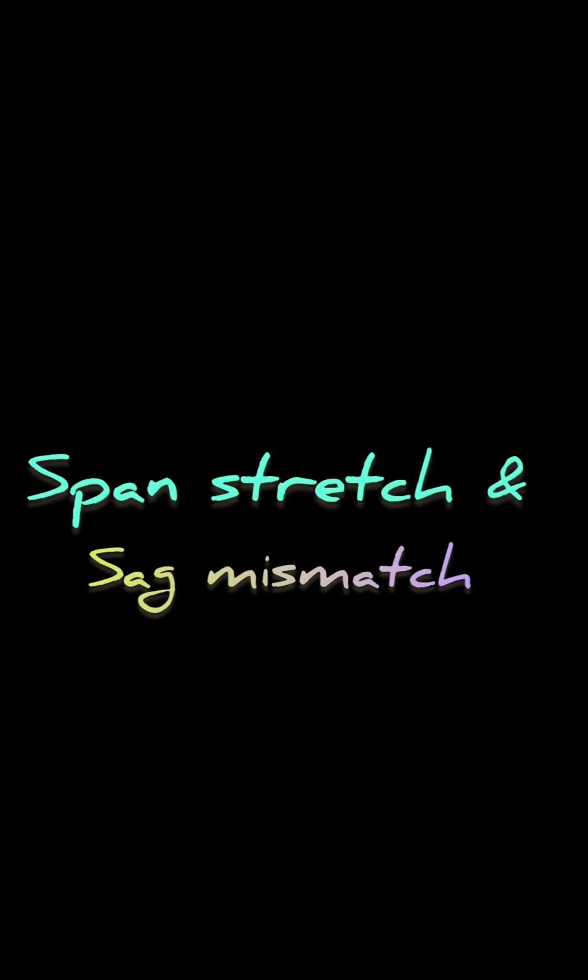Let's go to the next point, that is span stretch and sag mismatch. The span is going to stretch and the sag is going to mismatch between the different poles. Cause: pole leans. Effect: span becomes diagonal. Electrical effect: GMD or inductance or sag change, as we saw in the earlier video. Effective span L' = under root L square plus H square = under root 40 square plus 0.7 square, approximately 40.006 meter. Difference in sag or spacing is a minor phase imbalance, but not dangerous alone.